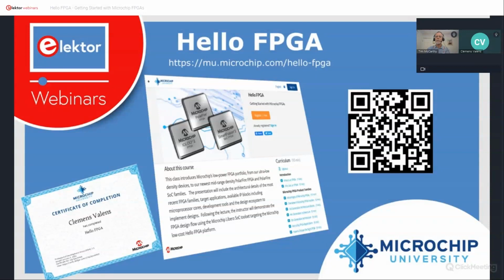The flash-based devices have the floating gate where we inject a charge during programming time, and that charge stays there until you erase the device and reprogram it. So the devices are almost instant on. And when I say almost, it's because the IOs have to be configured, and we have to have a combination of an IO voltage supply plus the internal supply for the FPGA core logic to hit certain thresholds. But basically, once your power supplies hit the thresholds, the device is going to be ready to operate. So it's ready to operate much faster than an SRAM based device.